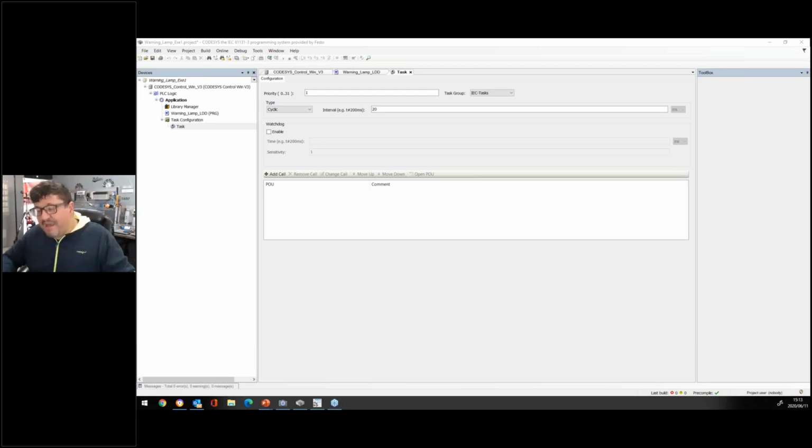What we can do is connect a Festo CECC CPU as a slave component within the Siemens world. You can also connect on Profinet. You can also make a Siemens PLC the slave in CoDeSys.